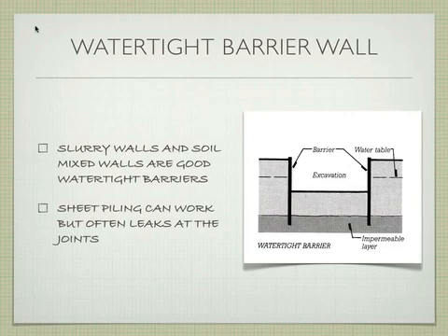So the last example is to use slurry walls to form a waterproof barrier. What you're going to do here is dig the slurry wall all the way down to where it gets to an impermeable layer. So think bedrock. You dig a really deep slurry wall all the way down to where it hits the bedrock, where the water can't seep around it. Water stays on either side. It's a waterproof barrier. You can excavate to your heart's content in the middle.